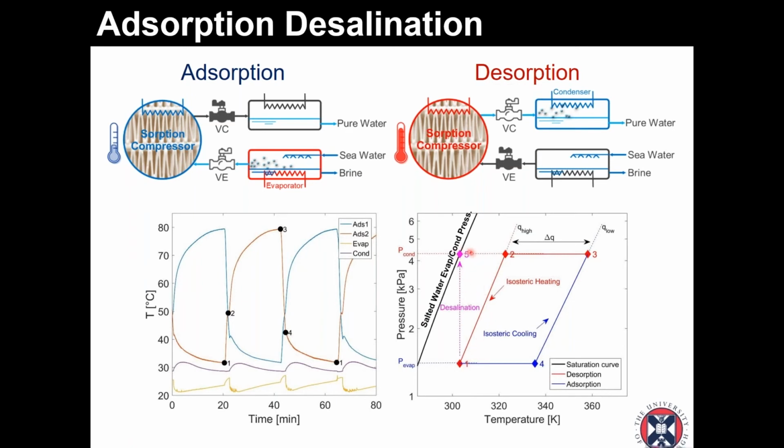If this comes closer here, let's say it's on a point here, the relative humidity will be pretty high, because the pressure that we can read is pretty close to the pressure of 0.5. The final message is that when we talk about adsorption desalination, we should expect a technology working at high relative humidities, where the adsorption bed works at high relative humidities.